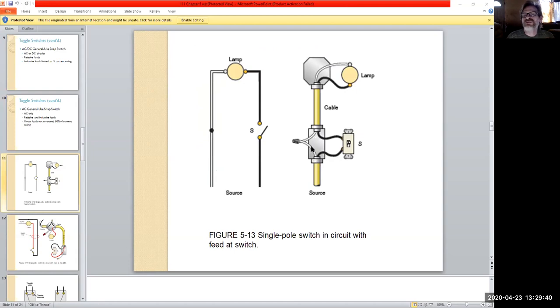And generally, you'd do the wire pull. So you would have a break in there. You cut it and splice it. And remember, each one of these has to be no more than 6 inches long. It's a good rule of thumb, pretty much as long as your hand is to the tip of your thumb. That's about an average of 6 inches. Measure it and see, and then you can eyeball it.